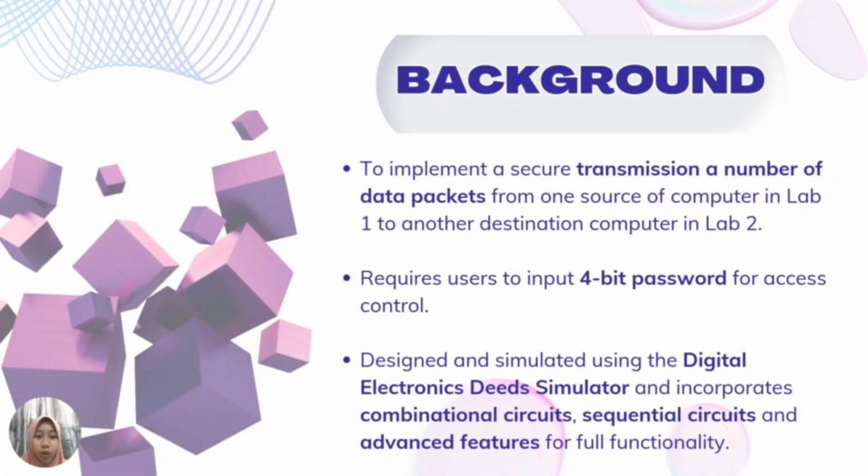Our project aims to implement a secure transmission of a number of data packets from one source computer in Lab 1 to another destination computer in Lab 2. Each lab contains 5 computers. The innovative design requires users to input a 4-bit password for access control. The entire circuit is designed and simulated using the Digital Electronics DISC simulator and incorporates combinational circuits, sequential circuits, and advanced features for full functionality.